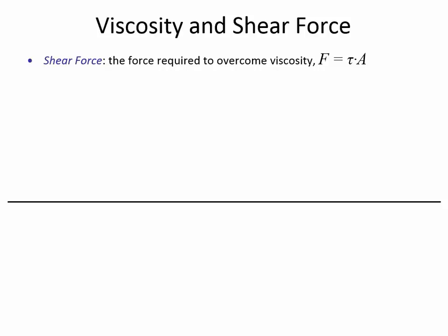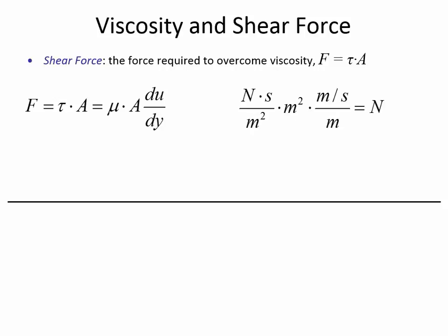All right. So if we go from shear stress to force, the way we do that is if you have a shear stress, which is newtons per meter squared, and multiply it by area, then you'll end up with force, units of newtons. So here's how we do that in the case of viscosity. du dy. Anybody remember what this grouping is called? It's the rate of strain. So if we multiply the rate of strain by the area that is in contact with the fluid, and we multiply that by the viscosity, then we will know the force required to cause that rate of strain, where the rate of strain is like a velocity. So when we're pulling on a plate, how much force is required to achieve a certain velocity is calculated with this expression. Here are the units.